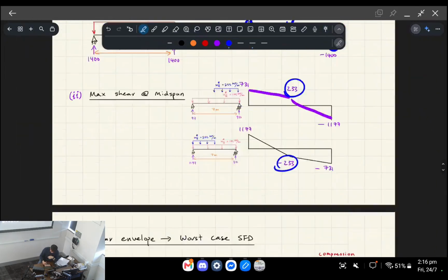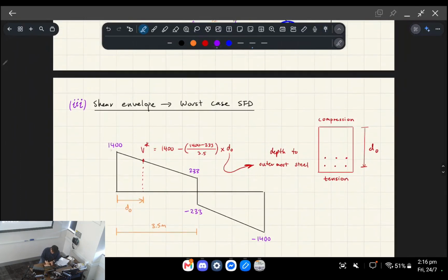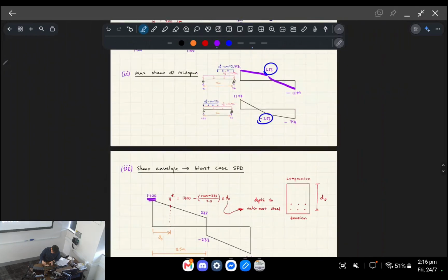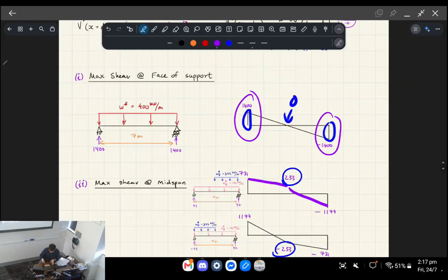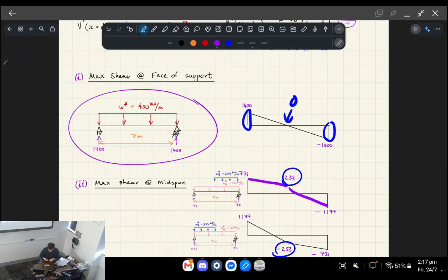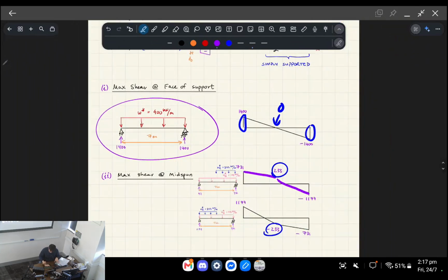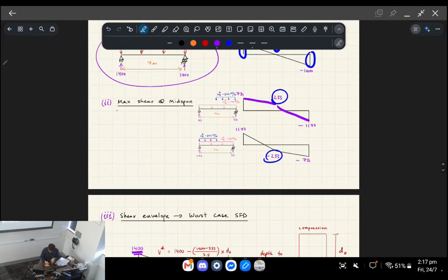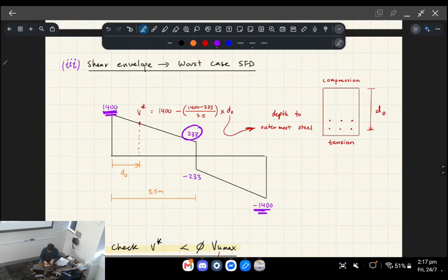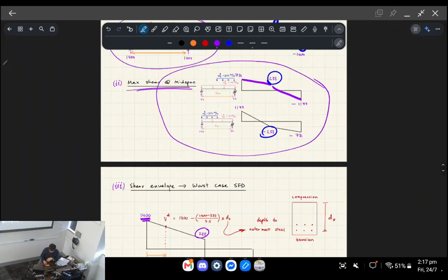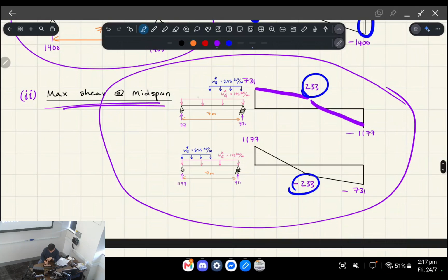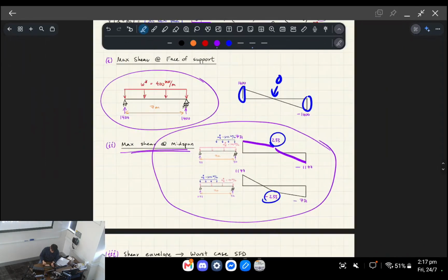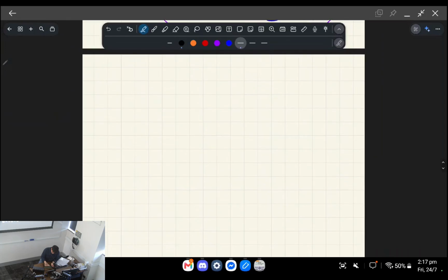Okay. So what does a shear force envelope look like? The supports, right, are going to take the max shear from the loading case where your ultimate distributed load is applied over the whole thing. But to find the max shear at the mid-span, it's basically plus or minus that number, okay? The number we found from analyzing the simply supported beam with the live load only applied over half of it, okay? Does that make sense?